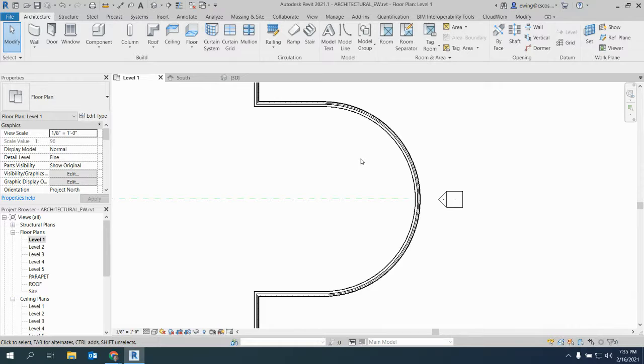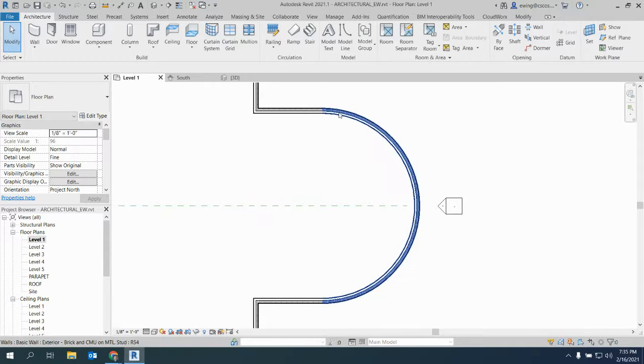So that wall system needs another wall system or structure to support itself. You generally don't see the aluminum and glass just standing there on its own. It has a hard time not falling over. So we're going to embed a curtain wall into this wall, and then next month or so we're going to actually add tube steel and we're going to support that.